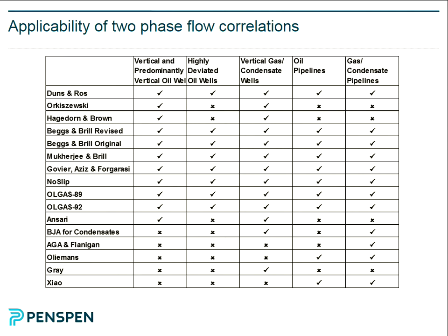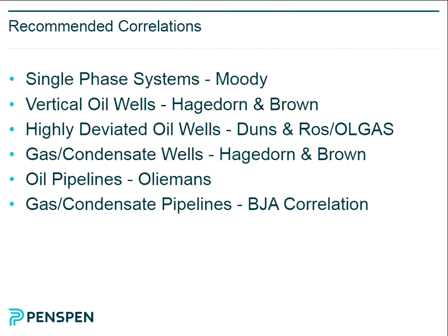So if you have very low flow rates, multi-phase flow can be incredibly inefficient, very, very inefficient. So that means if you want to promote efficient multi-phase flow, if you reduce the diameter of your pipeline, you increase the velocity, and therefore you promote more efficient flow regimes. So the diameter of the pipeline in multi-phase flow has another context other than just pressure drop. It's altering the efficiency of your multi-phase flow.